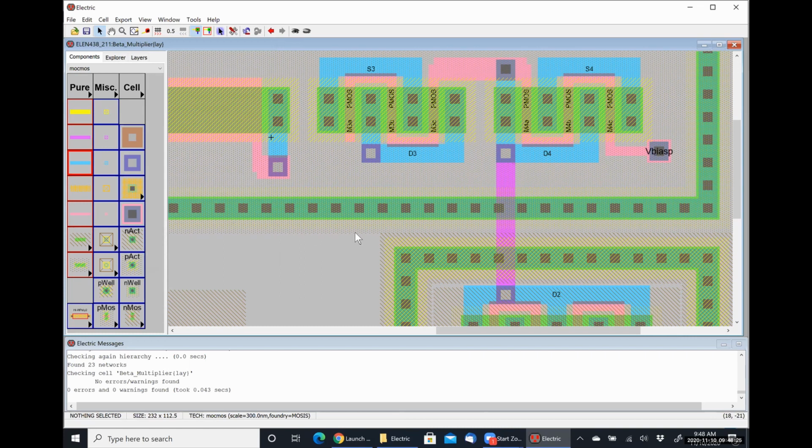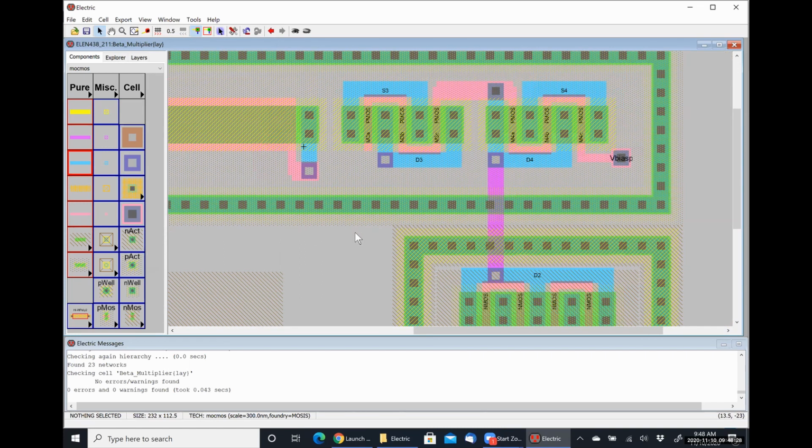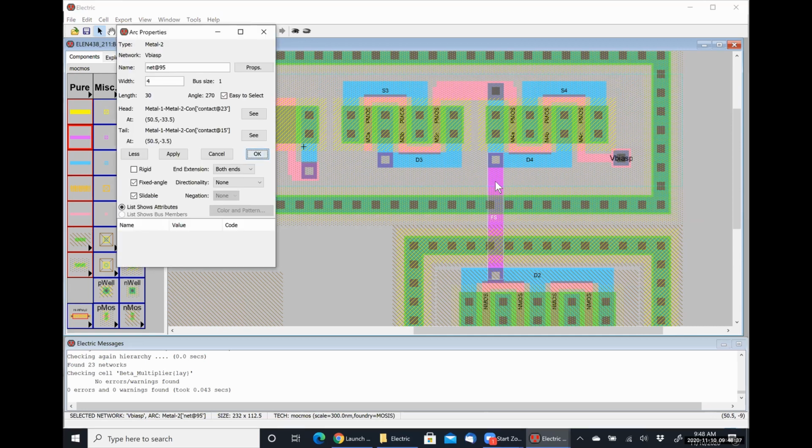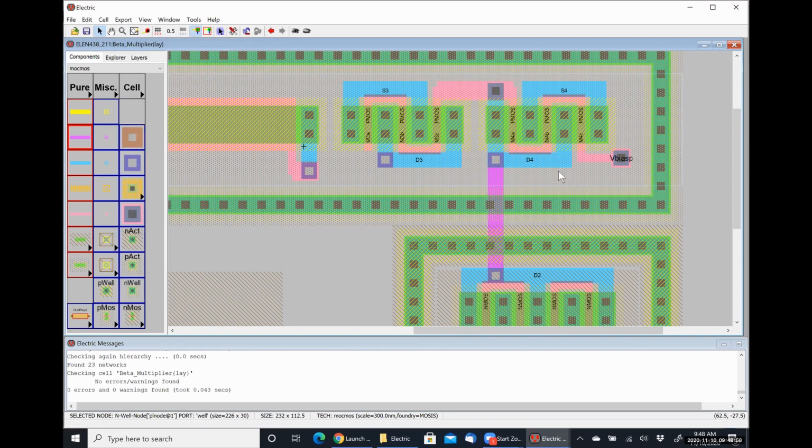All right, so that is the drain connection. I mean, that's metal. Let's see, it's 30 by 4, so that's 7.5 squares. Probably 7 squares. So that's on the order of like 1 ohm of loss resistance between those 2 points. What I'm trying to think is if I wanted to instead make multiple connections in parallel to lower that resistance, or just make one large wide connection to go across there.